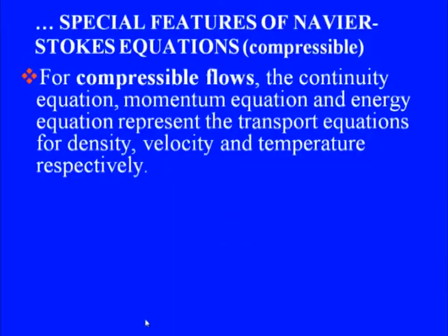equations. Now, if we deal with compressible flows, in the compressible flow continuity equation, it is essentially a transport equation for density, the del rho by del t, that is time derivative for density, and plus divergence of rho times V, that gives us the convection term for the density. Momentum equation represents a transport equation for velocity, and energy equation represents a transport equation for either total energy, or we can also transform it into the transport equation for temperature.